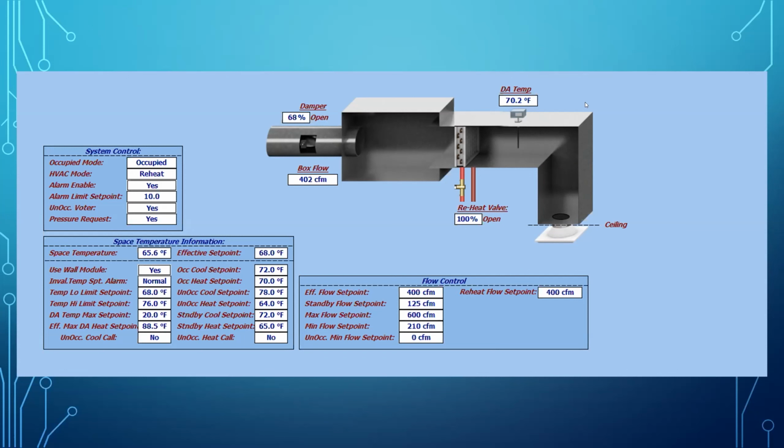So Bradley suggests, assuming hot water temperature is normal, either a bad reheat valve actuator or linkage is loose. So addressing the problem that this actuator here that we can kind of see on the graphics is malfunctioning in some form or other, which is definitely possible, especially given that our building is 5 to 6 years old at this point.